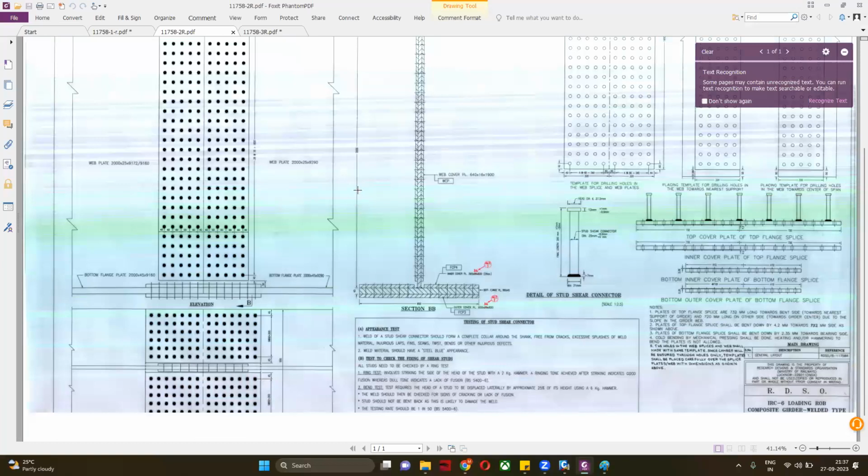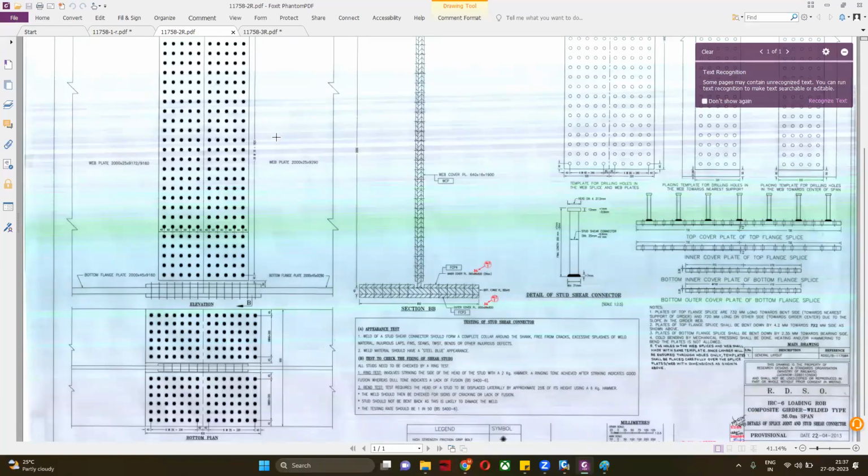These are the same web girder. Here we generally also use the deck. This is backing plate. What we do in the middle L by 2, we provide the flange, bottom flange maybe 50 mm, and as we go to the support, we provide flange as 25 mm. Then at connection, we change our plates.